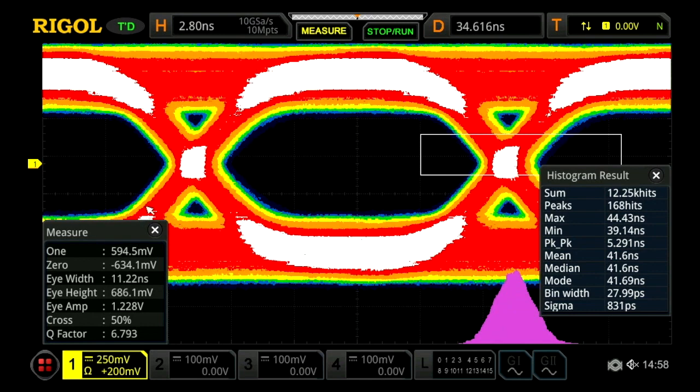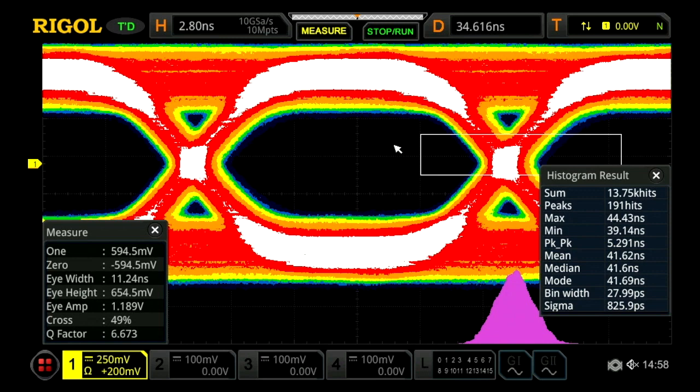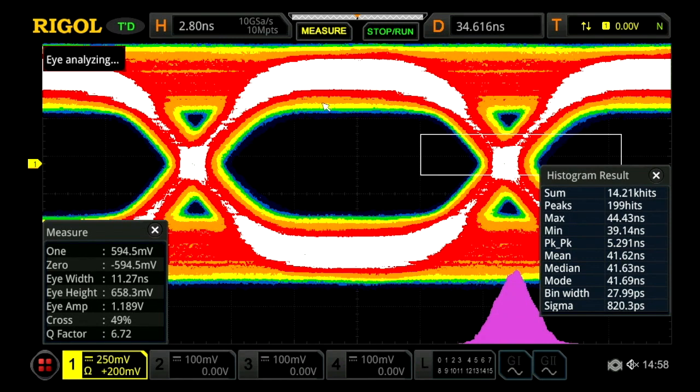Additionally, the rise and fall times on these transitions are pretty diagonal, at about 45 degrees. In these settings, we'd like it to be steeper, giving us clearer corners in this eye diagram. That's likely a bandwidth issue, not allowing the signal to change fast enough.